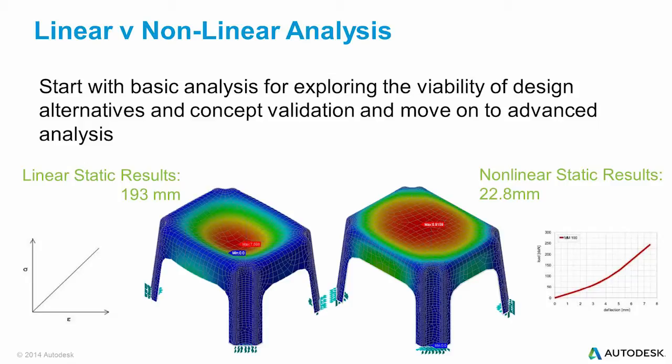So you may actually get lower deflection. If it softens, you may actually get larger deflection. So non-linear analysis will apply the loads in smaller steps and allow the stiffness to change for much more accurate results. This is very important if you're dealing with components which have a large surface area to thickness ratio, such as you may have with metal sheeting, for example.